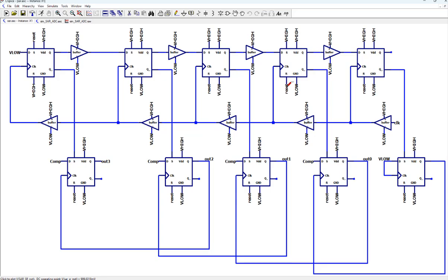So it's controlled by what? The comparator's output is being fed into where? Into the first D flip-flop of the code register, right? Actually, every single D of the code register. The sequencer will need to be running it. So this clock will run again. This clock is always on, right? So this clock will run again and do what? Shift the one over.